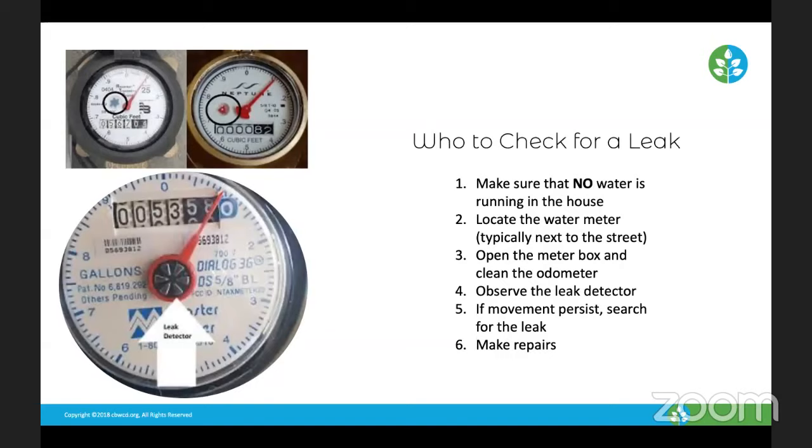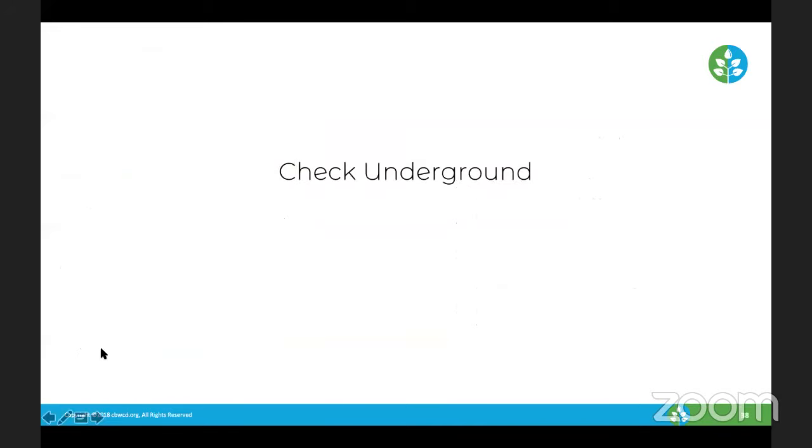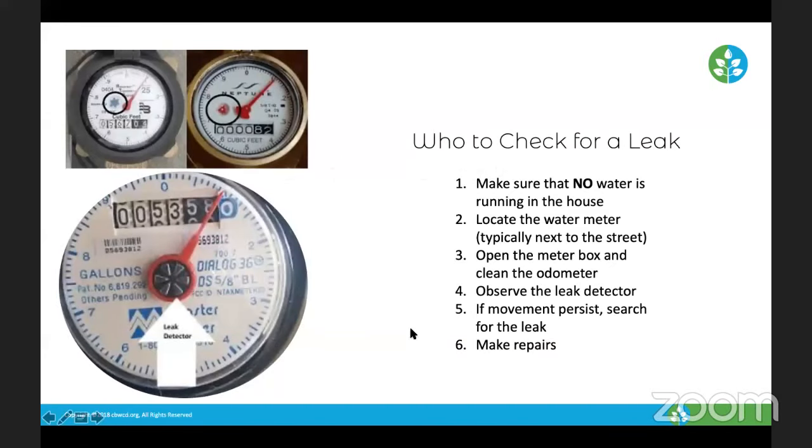I've gone to a lot of houses with issues like this. I've even seen where somebody has a hose bib way in the back of their property. They open it up every once in a while, use it, and close it, but this time they left it cracked open, and now their water bill went up four times because it's a constant leak, all the way in the back of the property. You're able to go in and look at that leak detector. It could be the same as a leaky faucet in the house or a leaky toilet. You would be able to see that low of a flow by this flow indicator.